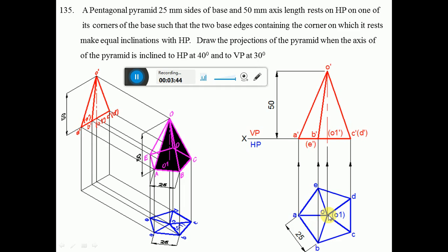Now we need to find out the center. So we have to draw the angular bisector. By using the protractor you measure an angle of 54 degrees with respect to CD, and then you draw a line. Similarly, from D with respect to CD you measure an included angle of 54 degrees and then draw a line. These two lines are going to intersect at this point, so you mark that point as O, and now you darken OC and OD.